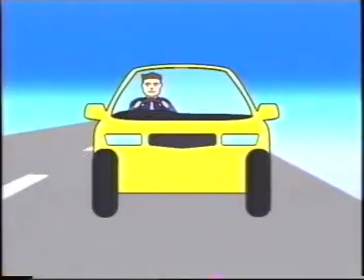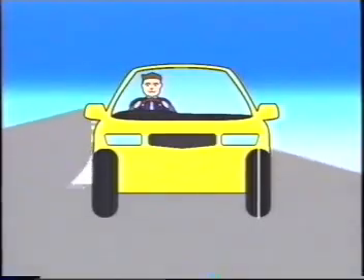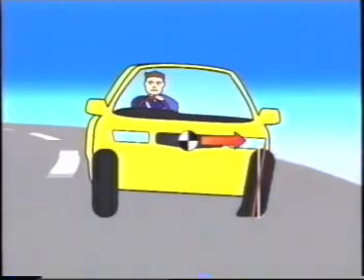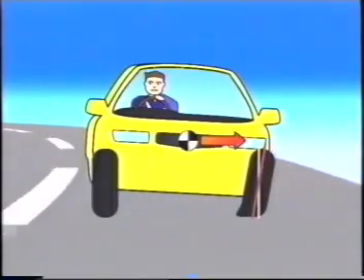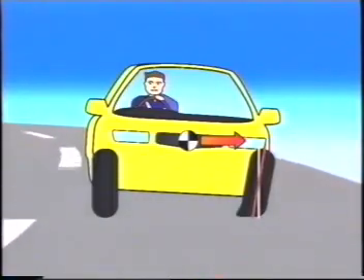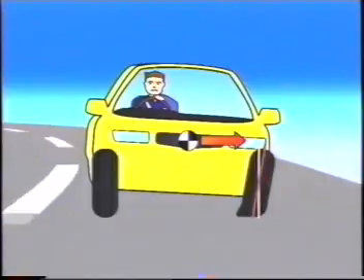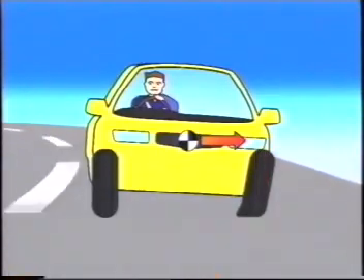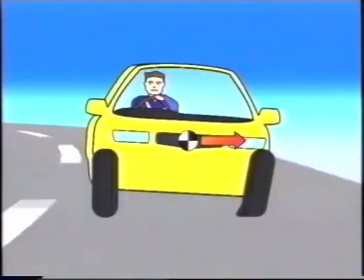When a vehicle is cruising straight, it is important for the tires to transmit the driving force directly to the road surface, making contact with the road surface at right angles. On the other hand, when a vehicle is cornering, the wheels on the outside of the turn tend to acquire a positive camber. This is especially true with independent suspension because centrifugal force causes the load to shift outward.